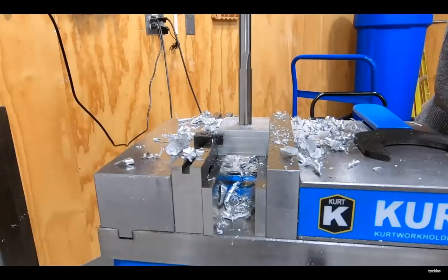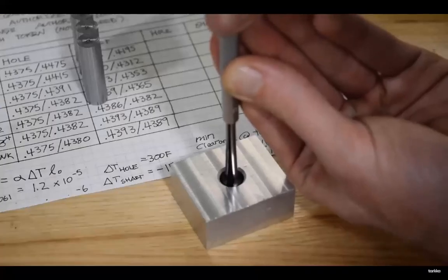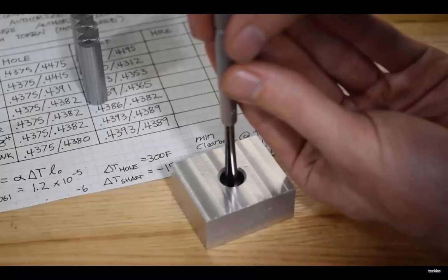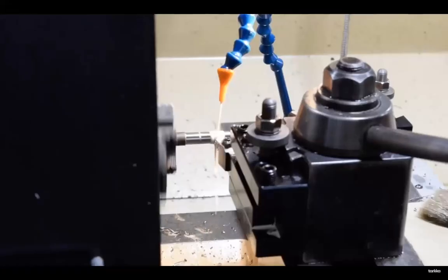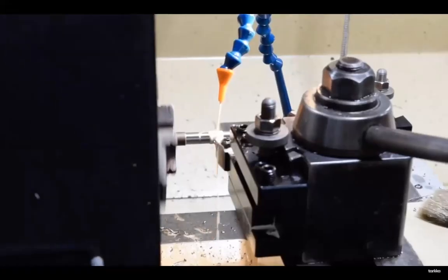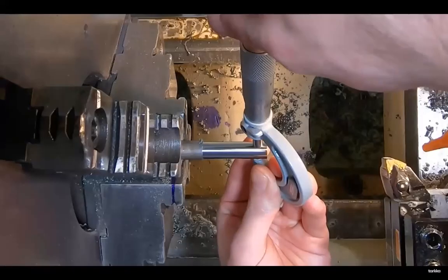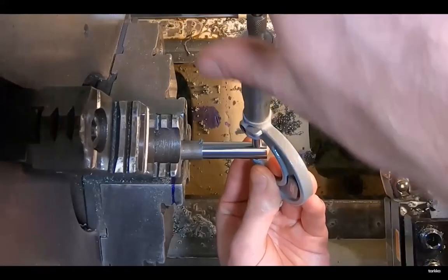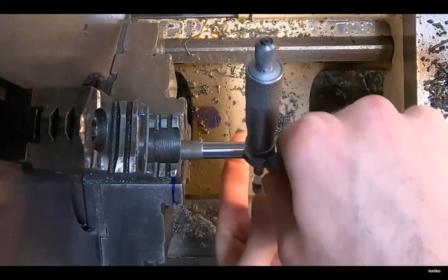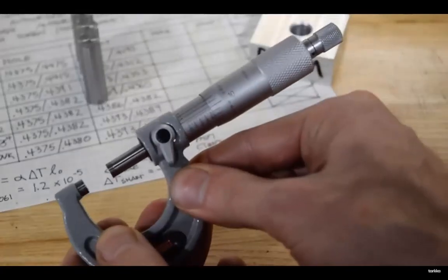This hole will need to be reamed or bored. You can also interpolate it on a CNC mill, but you will probably have to update the wear offsets throughout the production run to compensate for tool wear, and you'll need to be sure that tool deflection isn't causing the feature to taper with depth. A rigid lathe setup might be able to hit this shaft tolerance consistently, but as with the hole, you'll need to perform regular inspections throughout and adjust the wear offsets. A lot of parts, especially flexible ones or those made of tough materials, will require grinding.